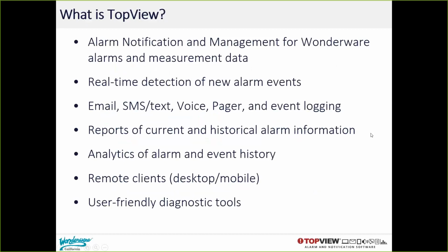So TopView is alarm notification and alarm management software for Wonderware. We typically monitor existing alarms, but you also have the option to create new alarm conditions against measurement data. The real-time TopView engine detects new alarm events, it logs these events, and it provides various forms of notification. The current and historical state of alarms can be viewed in scheduled and ad hoc reports, and our alarm analytics provides insight into your alarm activity to help you identify bad actors. Both current and historical alarm information can be accessed remotely through our desktop and web-based clients. And TopView's advanced diagnostic tools give you confidence in TopView by providing easy access to real-time performance information and to our logs.